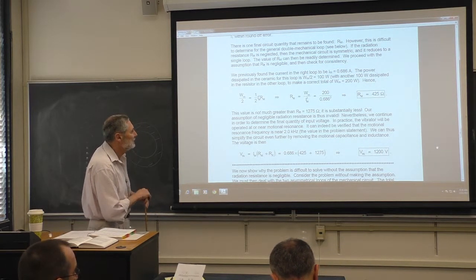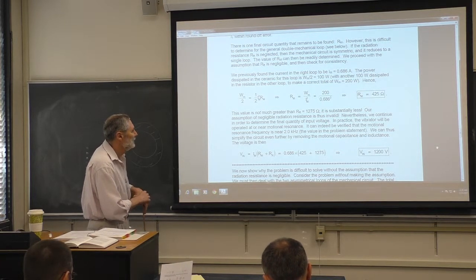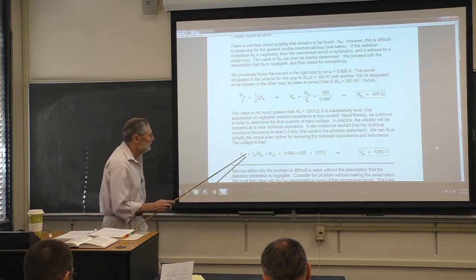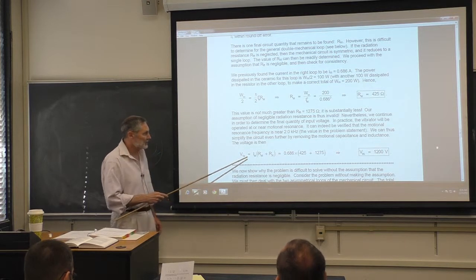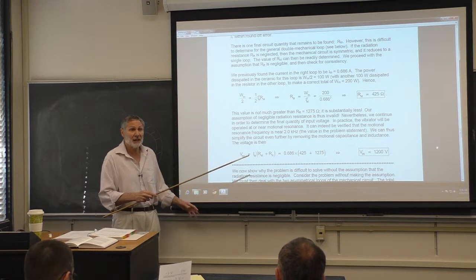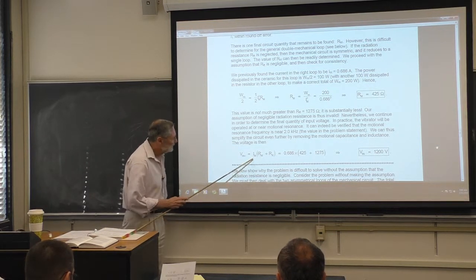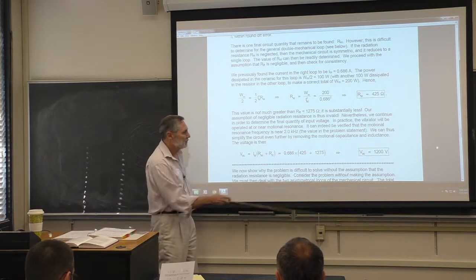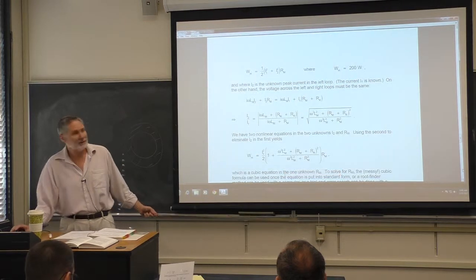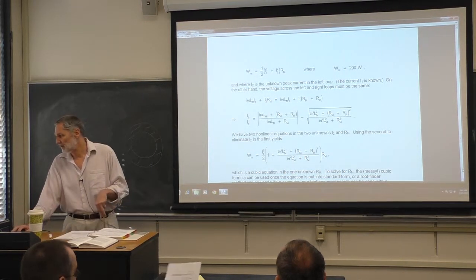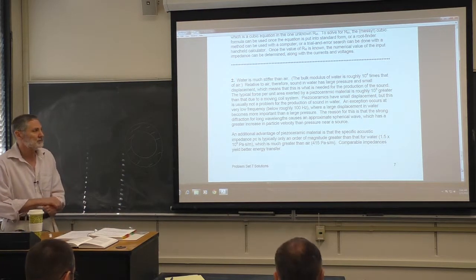Now, the final thing we're asked to do is the input voltage, I think. Looking at our circuit here, we'll just look at the right-hand side and get it on resonance. On resonance, we can forget the reactance, right? That's our friend. So it's just the current times the voltage here, and we get 1200 volts. Like I said, if you're interested in looking, this really becomes nasty. It could be done, but I don't think it's appropriate for a classroom problem. It's for research, maybe.